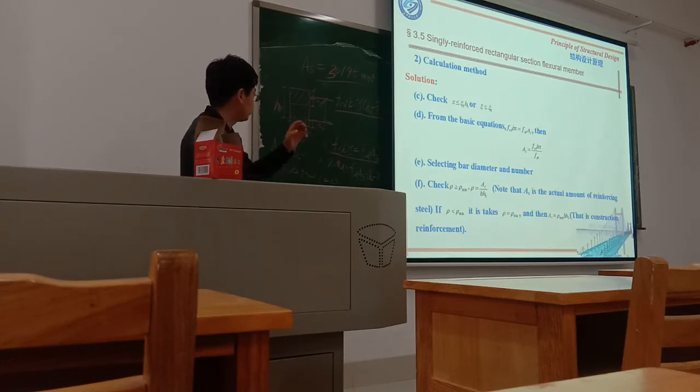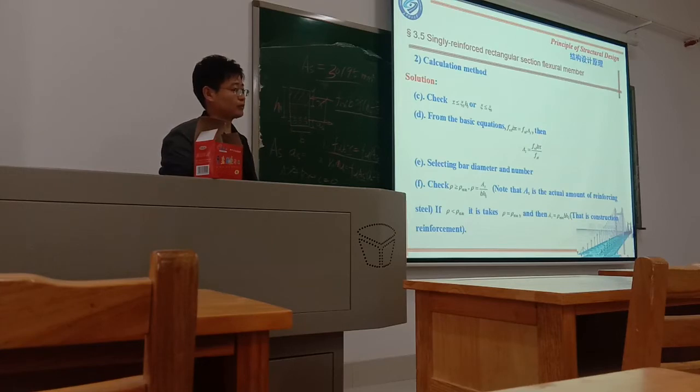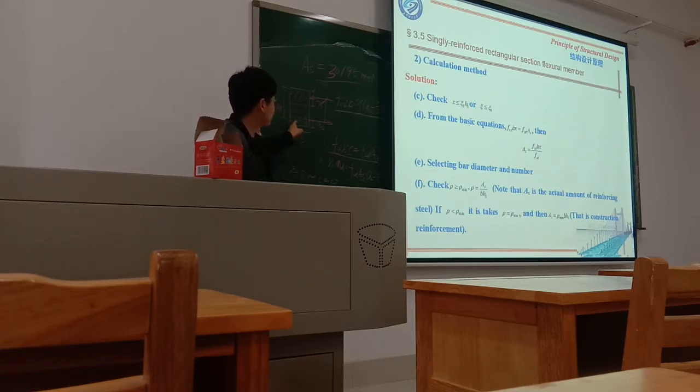Another principle you should remember: the arrangement of the steel reinforcement in this section should be symmetrical. If there are five reinforcement bars, you can make it one layer of 5, or two layers, the first layer 3 and another layer 2. But you should make it symmetrical.